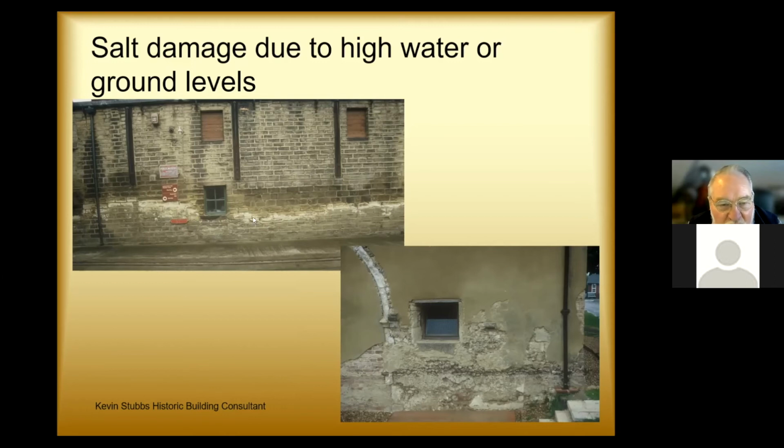You've got these seasonal fluctuations, where this stonework is wetting and drying all the time. And this is where the salts that were in solution have come out onto the surface and are blowing the stonework apart. And again, you can see that situation here being aggravated by dense renders.